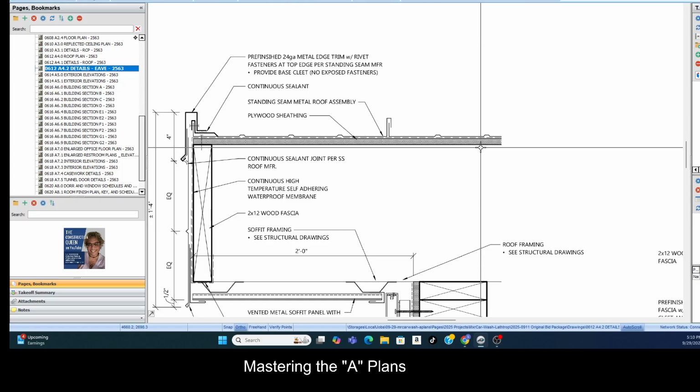So just like the framing, we're going to take linear measures along the perimeter of the roof, because this is all at the perimeter, right? The metal edge, the drip edge, the continuous cleat, and so on. So we're going to measure linears of that, and then we'll know how much we need. We do the segments just like we do framing.